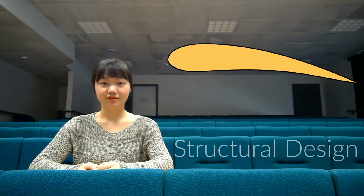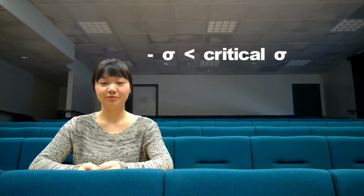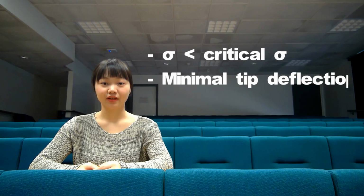Wind turbine blades experience large aerodynamic and centrifugal forces under high spinning speed. There are 2 criteria the design structure must fulfill. First, the stress in the structure should not exceed the critical stress of the building material, so the structure will not fracture during the test. Second, the blade tip deflection should not be excessive. Excessive deflection would induce severe vibration which may damage the structure.